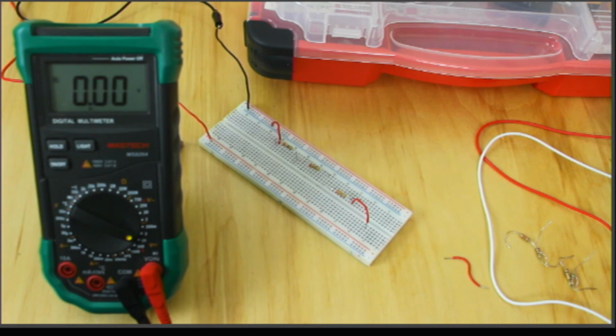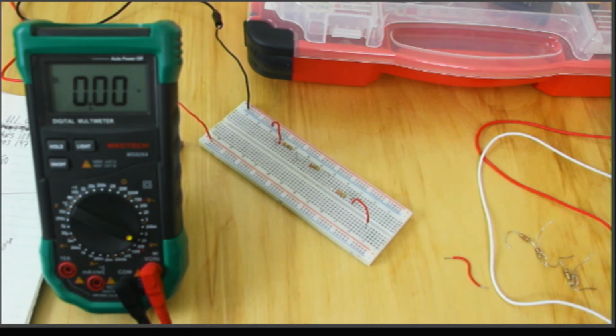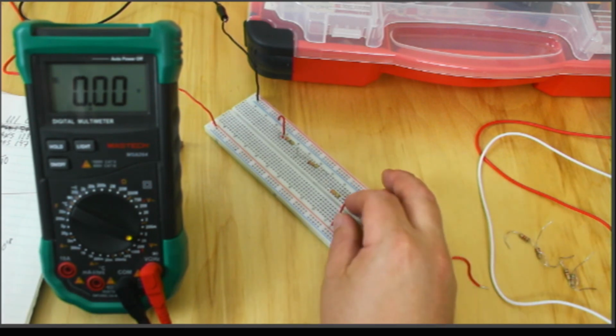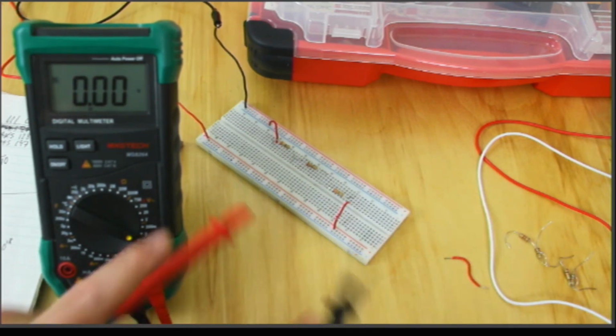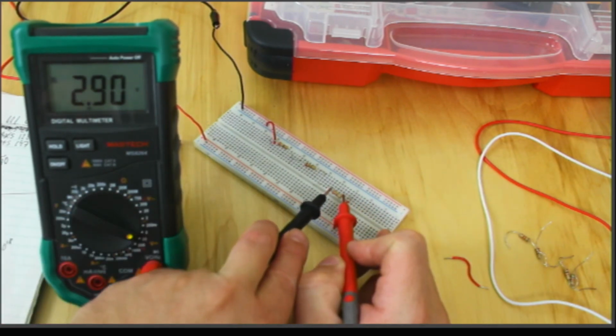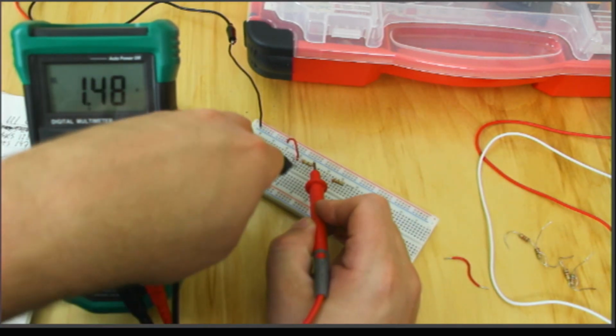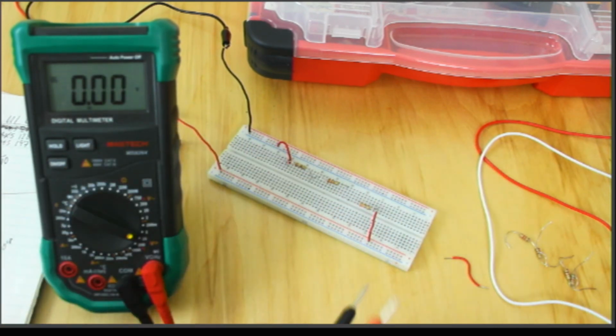Okay. So what I'm going to do is find my paper here, and I'm going to write down these, and I'm going to redo all the calculations with 8.25 volts. So that's what I measured. And then the first one was 2.9 volts. The second one was 1.92 volts. And I've already forgotten the third. I think it was like 3.4 or 3.42. Let's measure it again and see, just to be sure here. So I've got the circuit live again. 2.9, 1.92, 3.44. Works for me. 3.44.